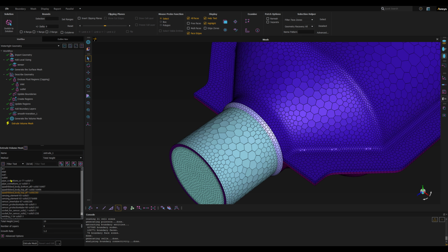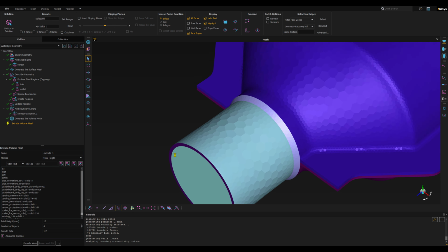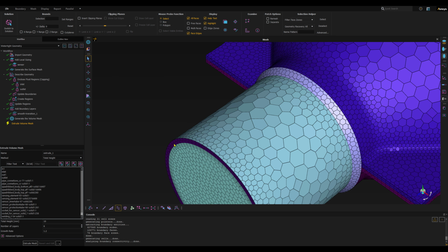For a start, you need to select your boundary that you are going to extrude from that surface. You can find it here, or just simply click on the region that you are going to extrude. In this case, I need to extrude this part, so just click on this part, and as you can see, this is in one, so you can find this region and this boundary here. Then I'm going to extrude 20 millimeters, for example, and the number of layers here is 12, for example.